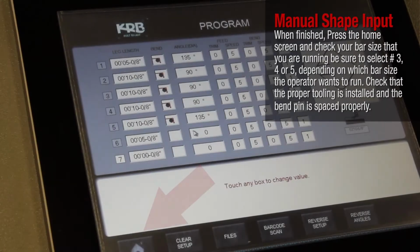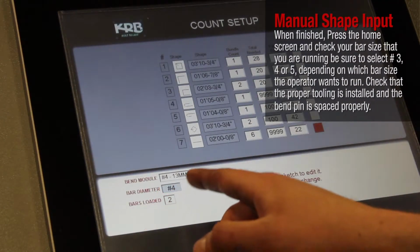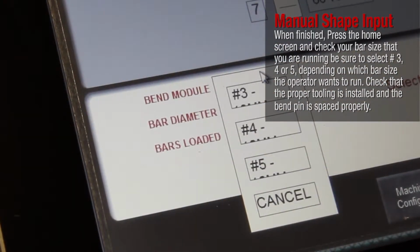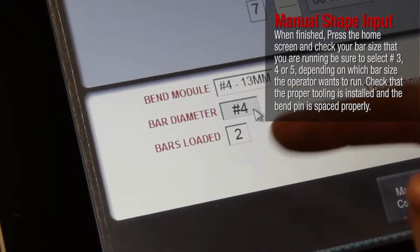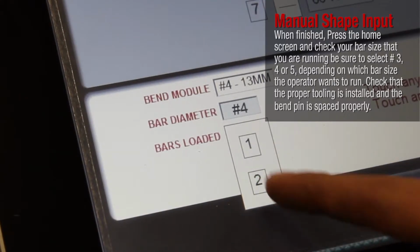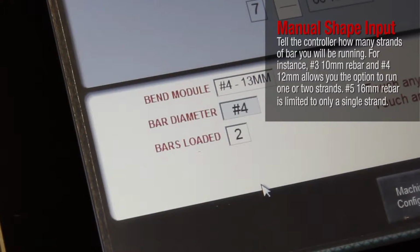Press the Home screen and check your bar size that you are running. Be sure to select number 3, 4, or 5, depending on which bar size the operator wants to run. Check that the proper tooling is installed and the bend pin is spaced properly. Tell the controller how many strands of bar you will be running.